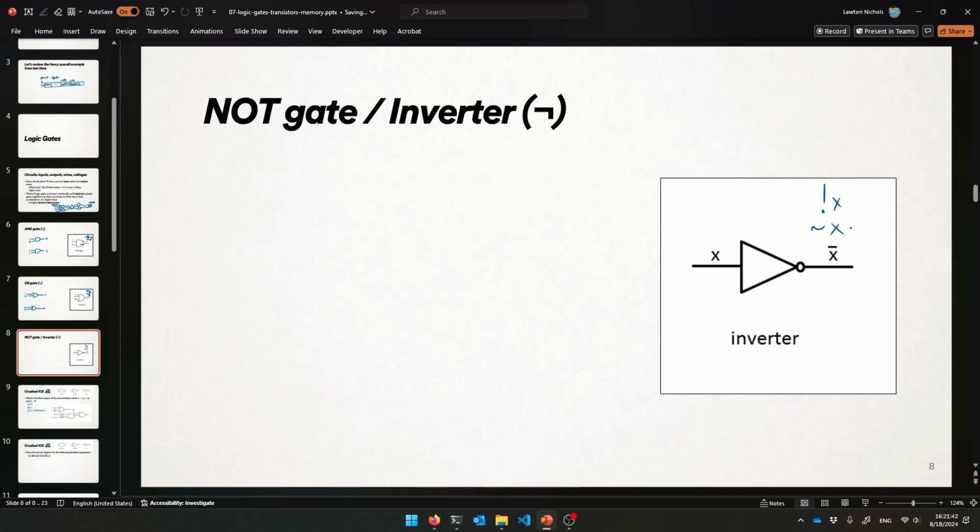And yeah, for reasons that will help when you're reading the textbook, I want you to think of the negation happening in the little dot right here, because that'll help you read other logic gates that you might read about. Okay, and that I will maybe show you later. So think of the negation happening here, and this is just bringing along the value for the ride. Negation's happening at the dot. Boop. And so, yeah, there's only two things I need to show you with a NOT gate, because there's only two things it could do. If there's a 1 coming in, it'll negate it to a 0, so true becomes false, false becomes true. Okay?